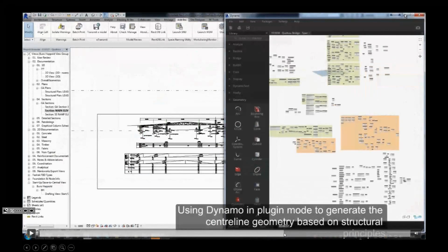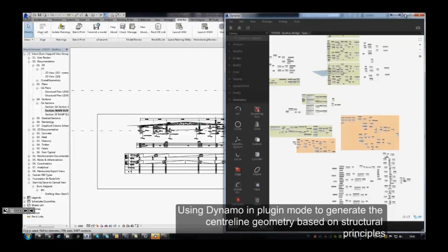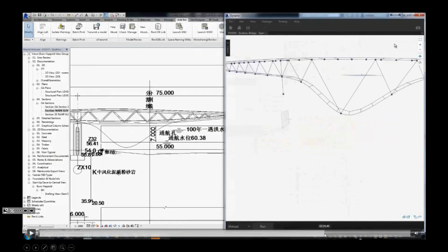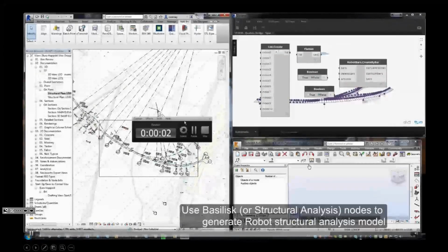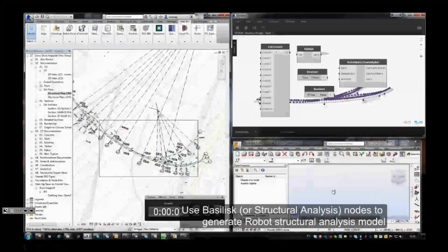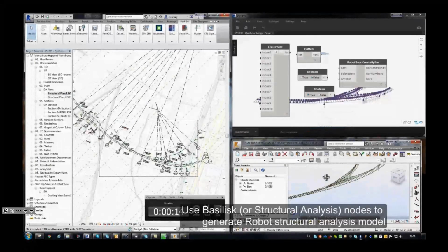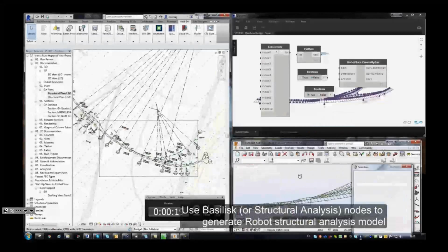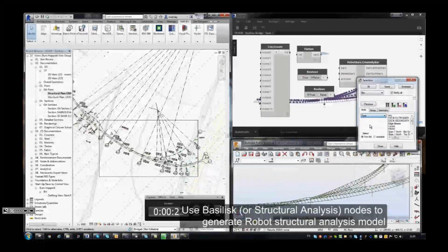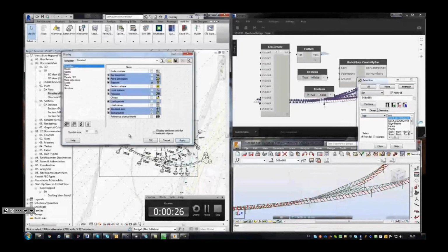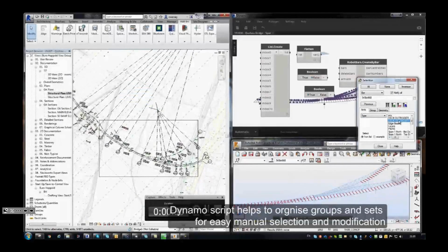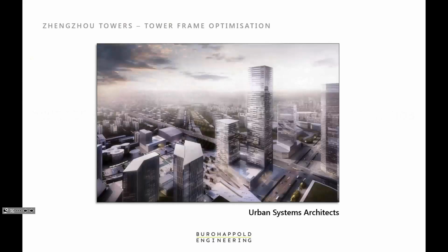That's a screenshot on the right-hand side of Dynamo, which is the Grasshopper equivalent for Revit. So Dynamo to Revit is what Grasshopper is to Rhino. And then finally, this is showing that all linking through to the structural analysis. The input is 2D AutoCAD, that drives the rules to generate the 3-dimensional sticks for the bridge, and that in turn is exported to the analysis software to get an idea of those eccentric and torsional loads on the piers.